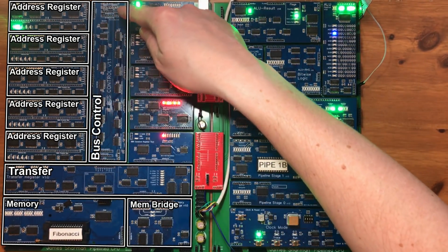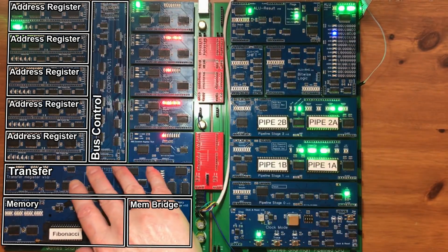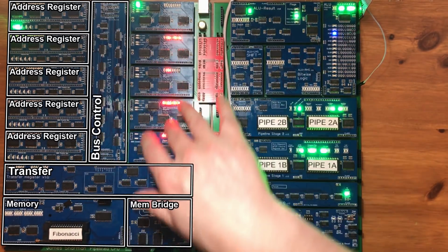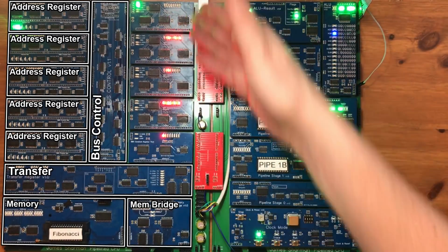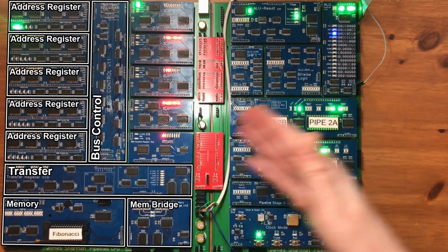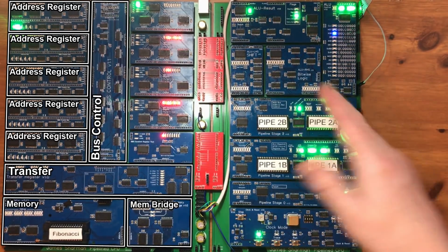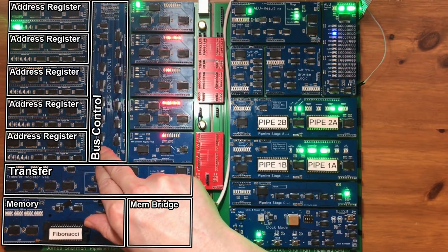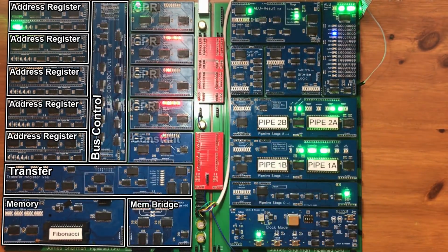Down the middle between the registers is the bus control. What that does is decode some of the outputs from the pipeline and turn them into control lines that are used by the registers. So for example, the device that's currently asserting onto the main bus comes from pipeline stage 2 as a 4-bit index, and the bus control has a couple of demultiplexer chips that will turn that into individual control lines that are wired into the registers.